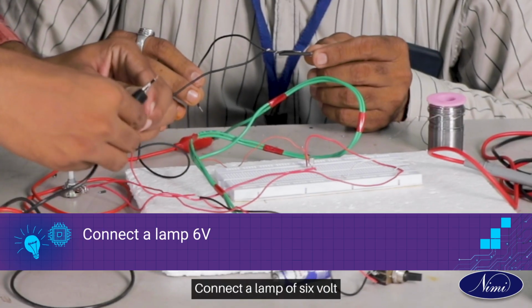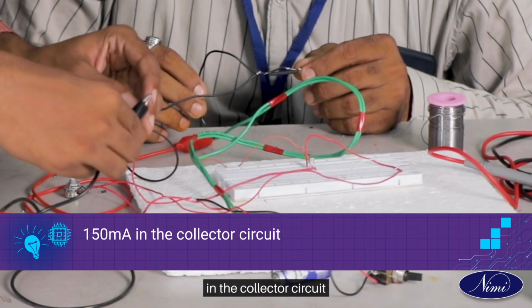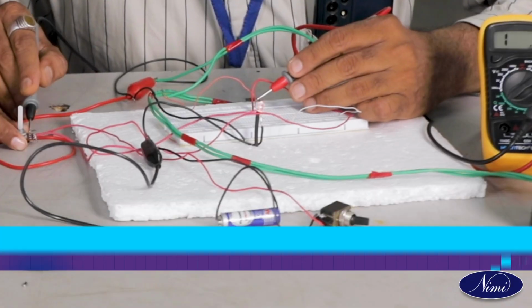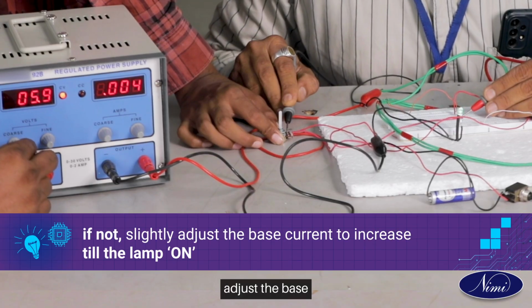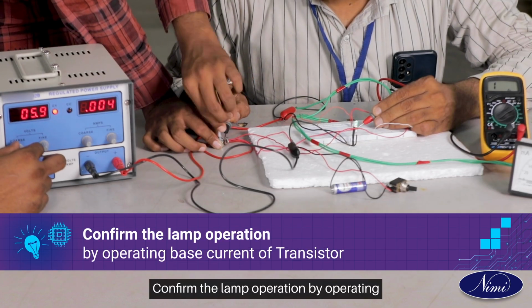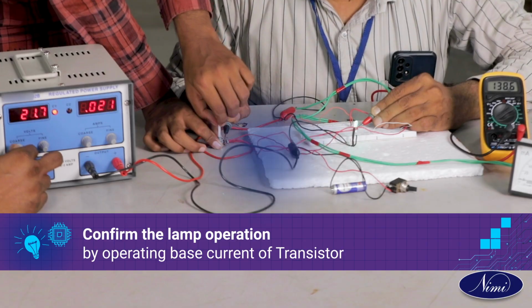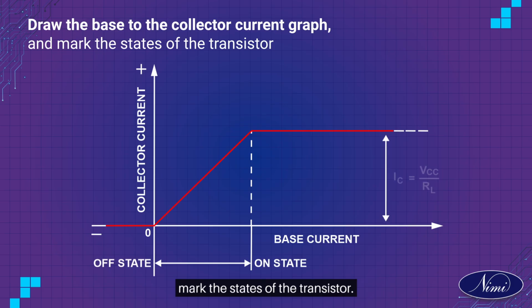Connect a lamp of 6 volt 150 milliampere in the collector circuit and switch on the power supply. Check lamp glowing. If not, slightly adjust the base current to increase till the lamp is on. Confirm the lamp operation by operating base current of transistor. Draw the base to the collector current graph and mark the states of the transistor.